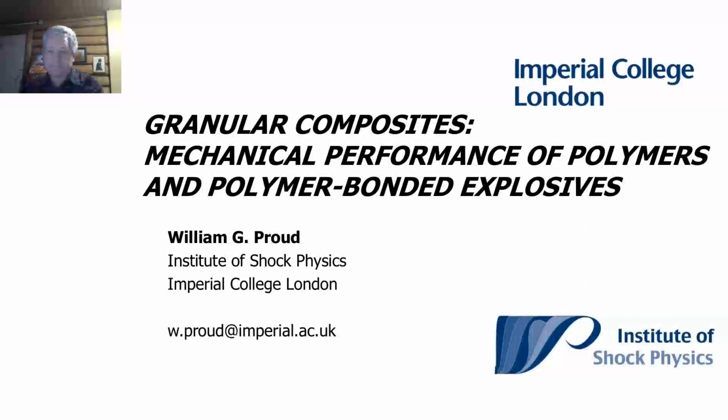On the impact face, this mainly polymer region becomes very stiff under the shock impact and tends to fracture. What we also know is that if you have a very stiff polymer, it's far easier to ignite the energetic material due to the cracks now running through the energetic crystals and not trying to go around them.